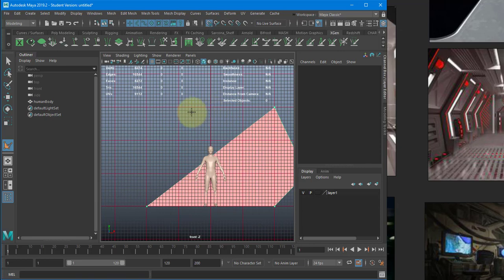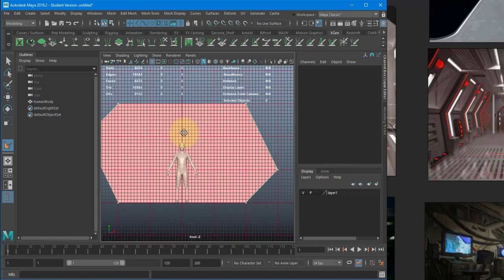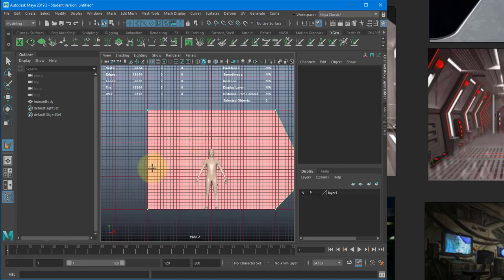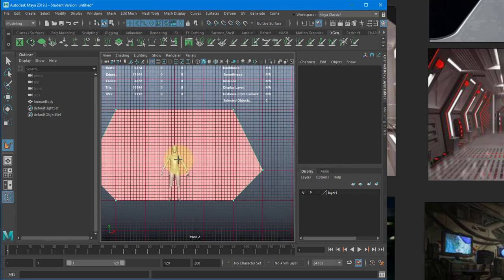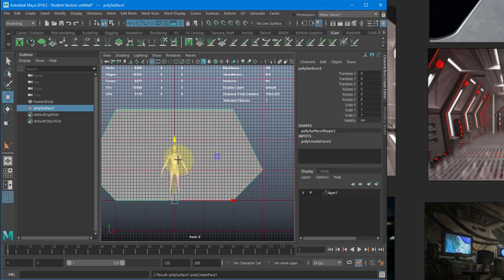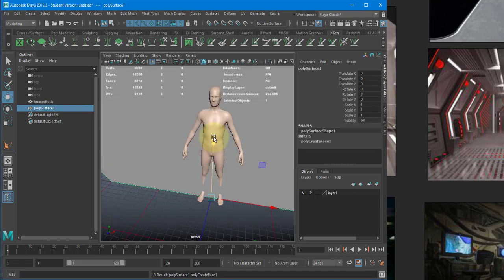And I'm just going to mirror that on the other side. So this is 2 red over. I'm hurting my eyes doing this. Do that, do that. Oops, see, I messed up, so I'm going to hit backspace. I'm going to hold X again, click there. All right, so there's the framework of my hallway. And then I hit enter, okay?